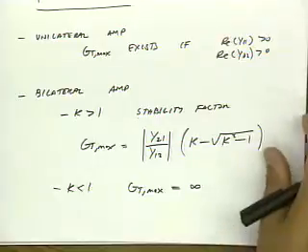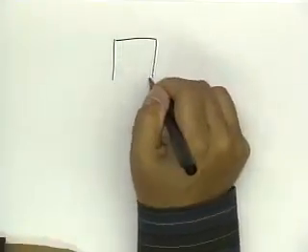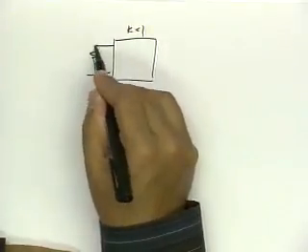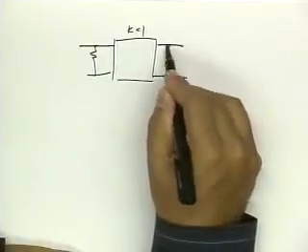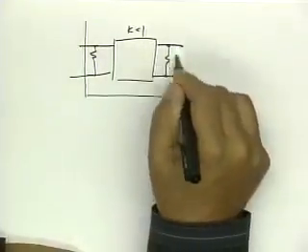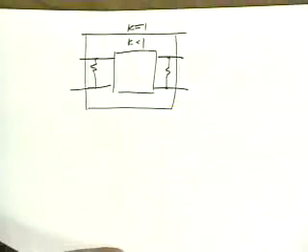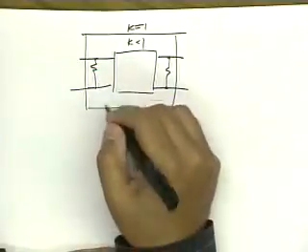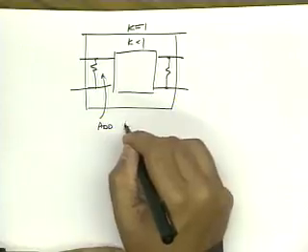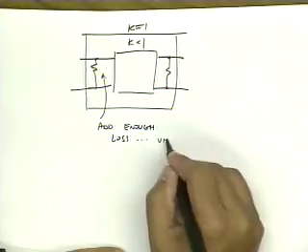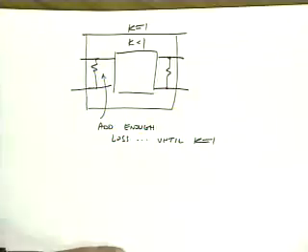And so with the intuition that we just got from the last slide, we can take our two-port, let's say K is less than 1, and add loss to the input and the output, so that we keep adding loss until we hit the boundary, K equals 1. So we add enough loss until K is equal to 1.